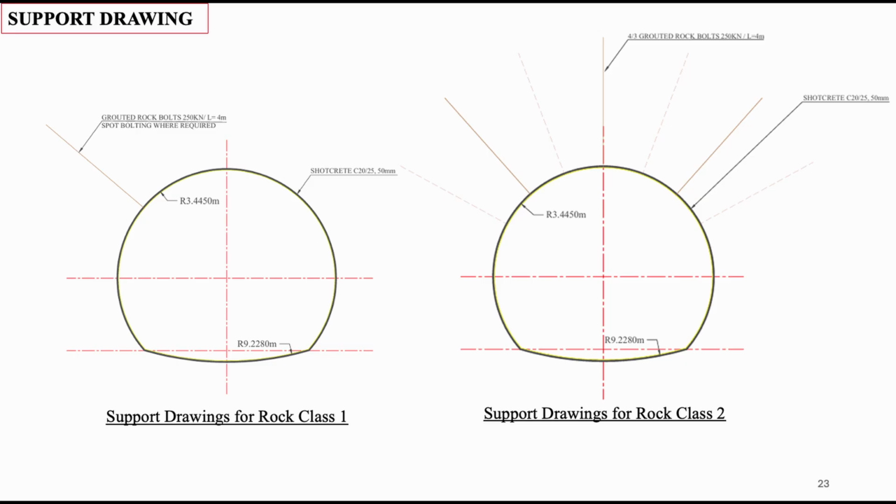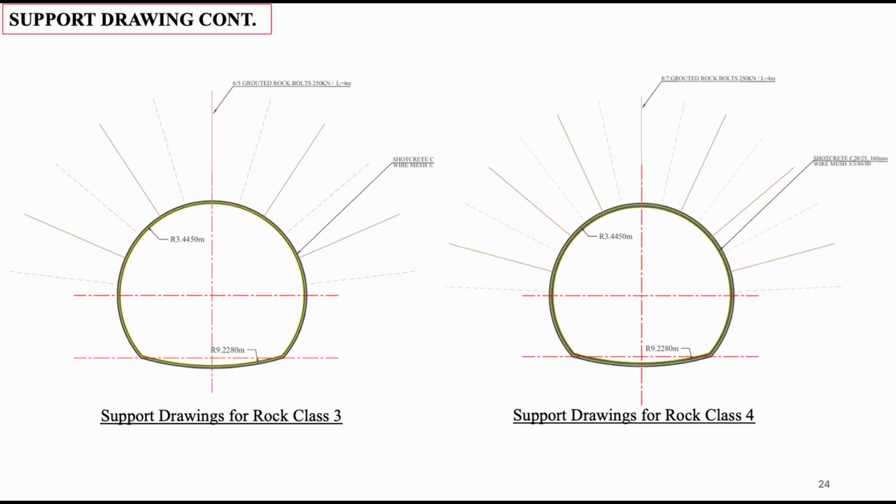We use self-drilling spiles to avoid drill hole collapses. Here, we have chosen span lengths and overlap lengths to keep the simply supported beam at better safety. And also, we recommend using a configuration of 50 millimeters thickness of shotcrete to avoid face collapse at the tunnel face.